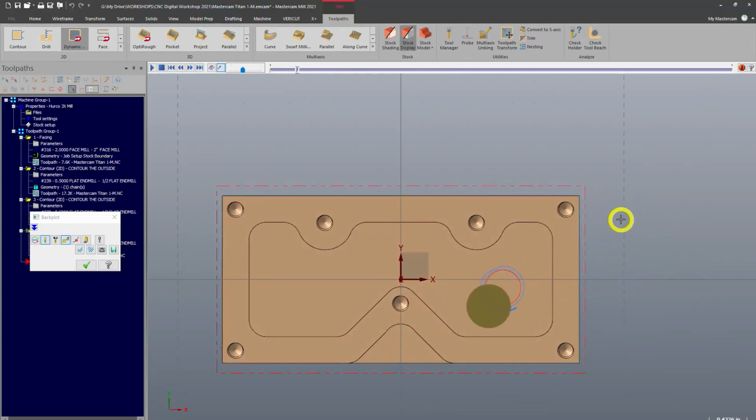And as it gets down, you can see those small cutting overlaps, and it's kind of peeling away the material, which is really good for tool life. Again, it's distributing the force of the cut along the whole length of the tool, as opposed to a standard pocketing toolpath where you might only be cutting at the tip of the tool, maybe a 1/4 inch deep.